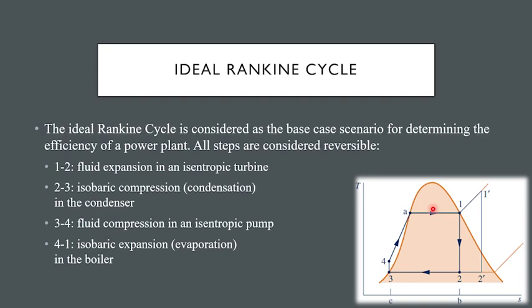Before we proceed, let's go back to our understanding of the Carnot cycle. If you will remember, the Carnot cycle under the temperature entropy diagram is rectangular in shape. We can actually trace the Carnot cycle here and compare it to the ideal Rankine cycle. The Carnot cycle starts with stream 1 here, which is a saturated vapor. It is then compressed isentropically to stream 2, which is a saturated mixture, and then compressed isothermally to a certain point here, and then expanded isentropically up to the point that forms a rectangle on the TS diagram.